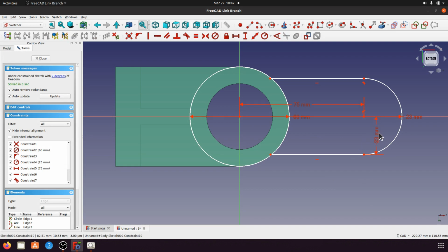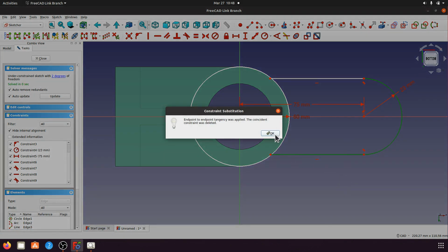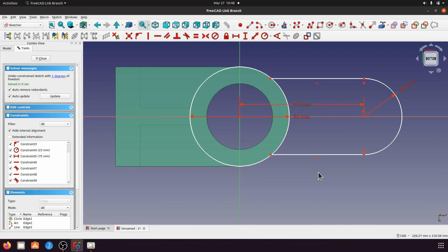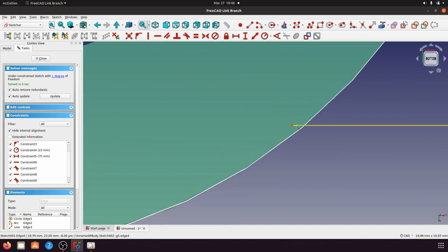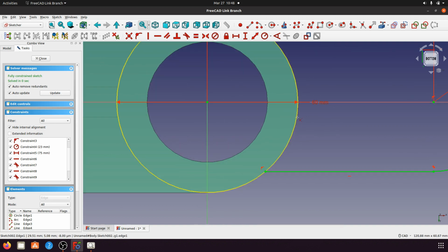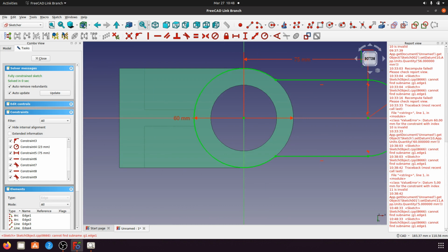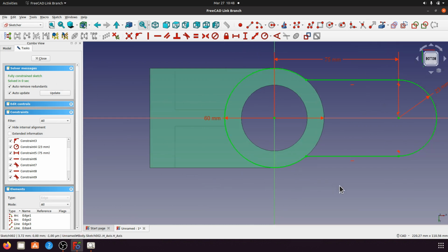Okay, I think it's the same whether this is tangent or the create dimension, or maybe we can delete and create this circle with the line for tangent. Okay, now we can cut this line, and this line, and also the circle. Okay, it's fully constrained now.